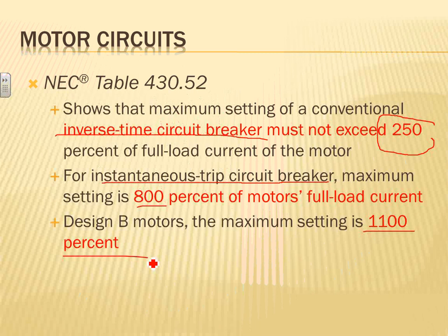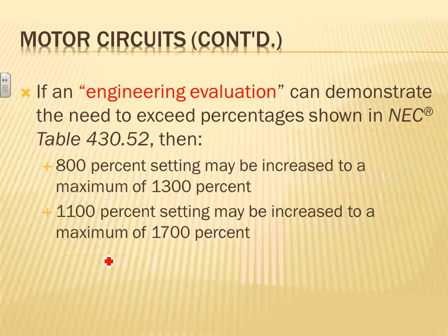The 800 amp is not going to be that big. These are specially designed circuit breakers. Size-wise, they are not that big, the instantaneous trip, but they don't have the overload component. They only have the instantaneous. It used to confuse me later on. I don't know if it confused anybody. When you see an instantaneous trip circuit breaker 800, you think it's that 800. This is not the full load amp rating of that circuit breaker.